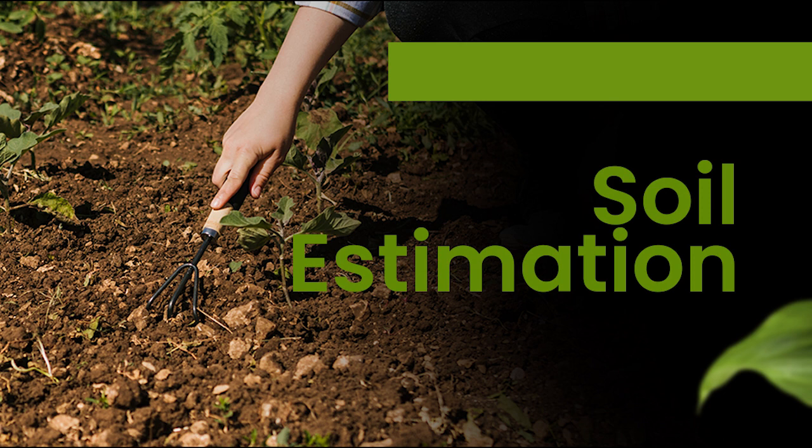For the other three, the first component is the topographic factor, which is the LS. So let's say something small about the topographic factor. It consists of slope length and slope steepness, which is L and S. Increase in the slope length causes increase in erosion due to a progressive accumulation of runoff in the direction of downslope. Increase in slope steepness factor S increases the soil erosion as a result of increasing velocity.